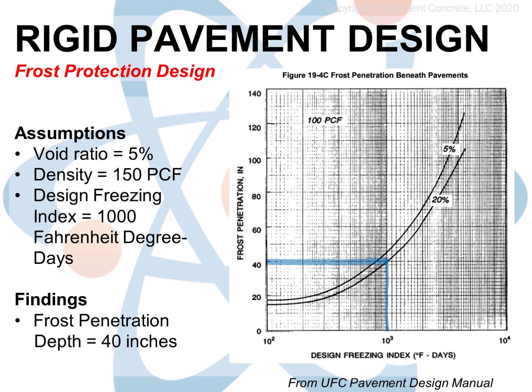Remember how I said dense soil allows deeper frost penetration? This chart is typical of its type, prepared for a variety of soil densities and water contents. Soil that is very dense could be very dry, perhaps as low as 2%, but soil that is native and not very dense could have quite a bit of moisture in it, since there's a lot of room for air and water. In our example, we're going to assume that we have soil that is 100 pounds per cubic foot with a 20% moisture content. Remember that we said our native soil was 20%? We didn't mention the soil density, but 100 pounds per cubic foot would not be too far off.